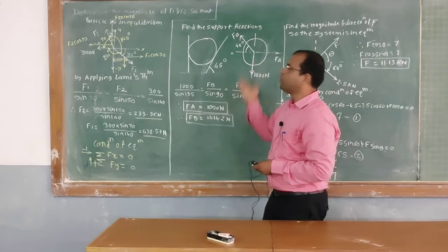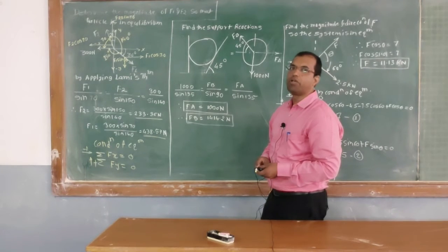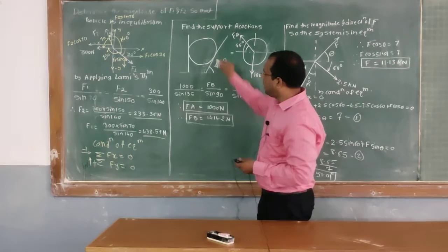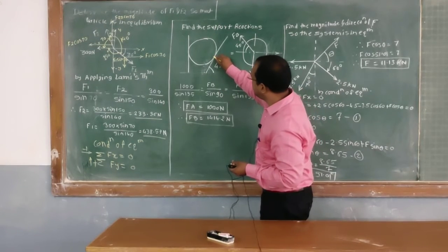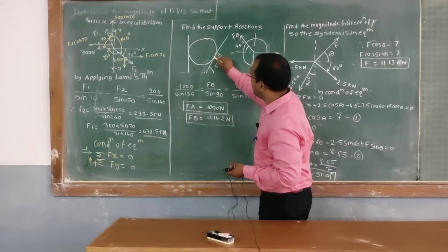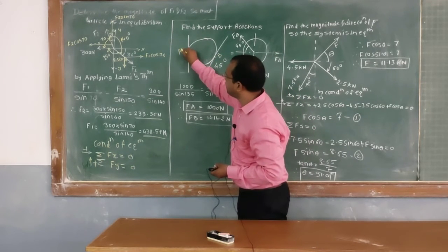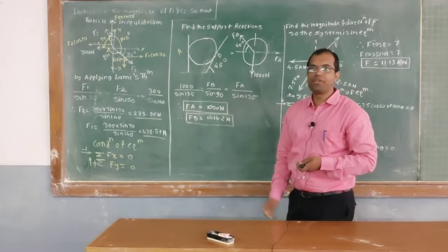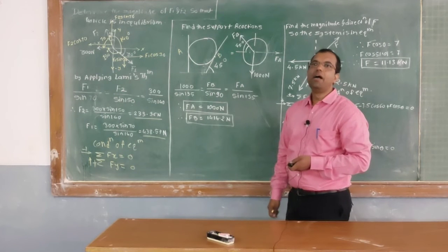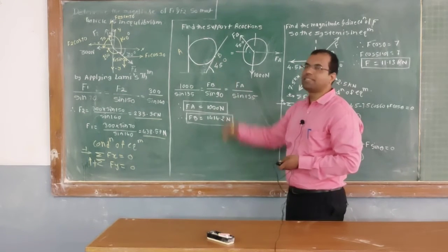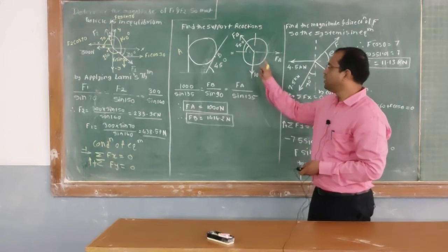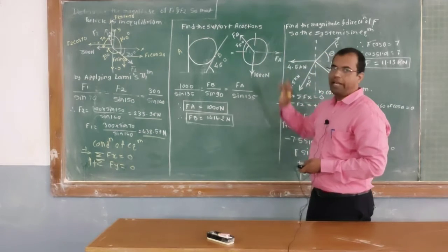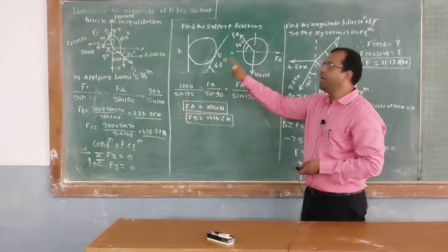Okay. Now here it is important to draw the free body diagram. This sphere is resting against the vertical wall. There are only 2 points of contact. Let's say this point is B and the other point of contact is A. At the points of contact the walls offer reactions on the sphere, so these are the reactive forces. And what is the active force in this case? Only its weight. The weight of the sphere is given as 1000 Newton, and we have to show the reactions offered by the supports at points A and B.